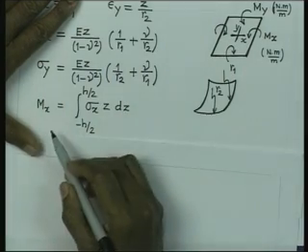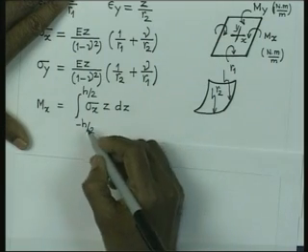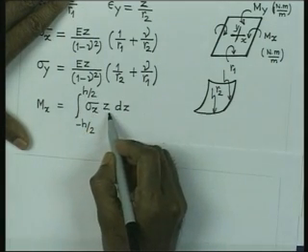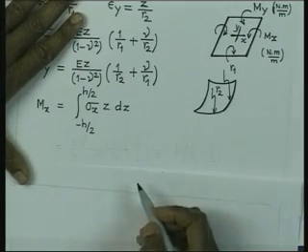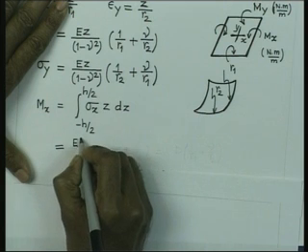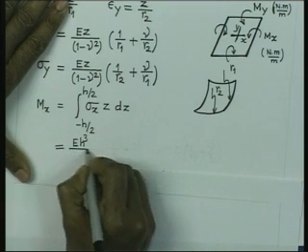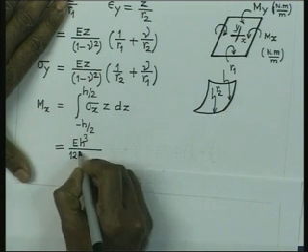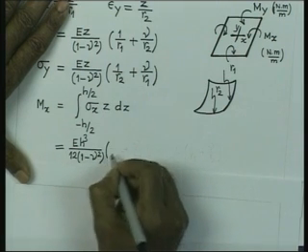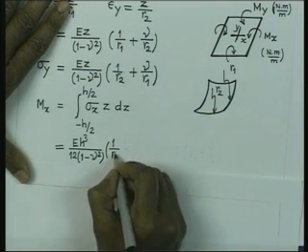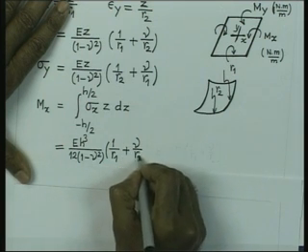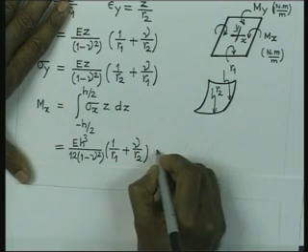So, we will have the moment in the x plane, Mx, is nothing but the integral from minus h by 2 to plus h by 2 of sigma x into z dz, and this will give us E h cube by 12 into 1 minus nu square into 1 by R1 plus nu times 1 by R2.